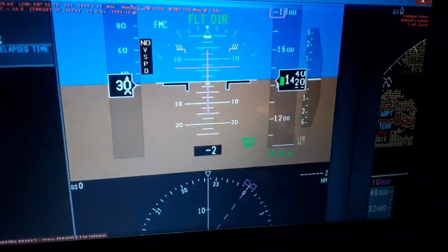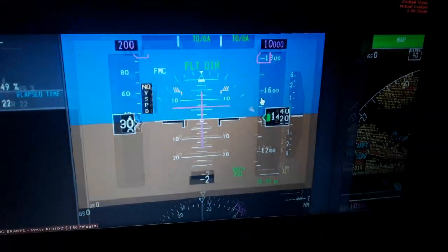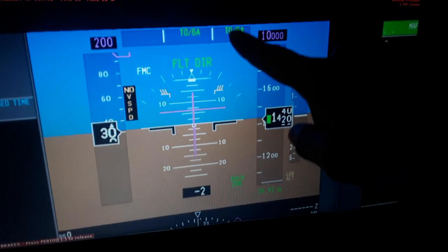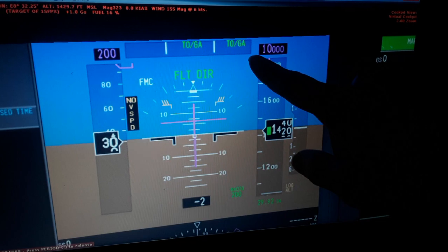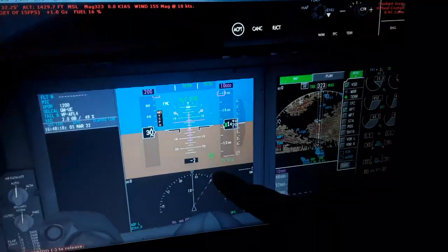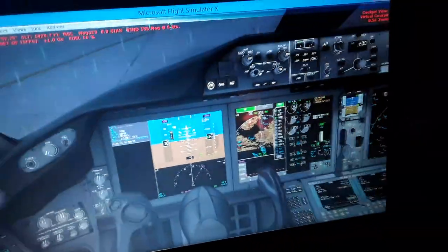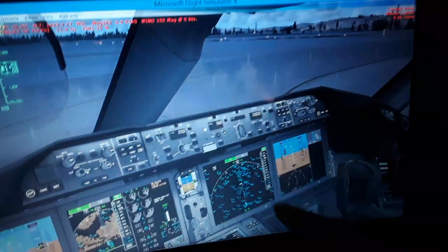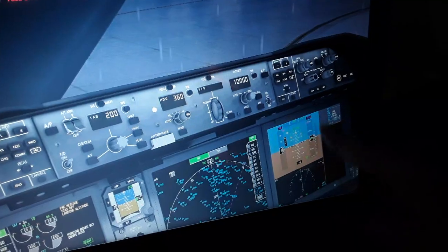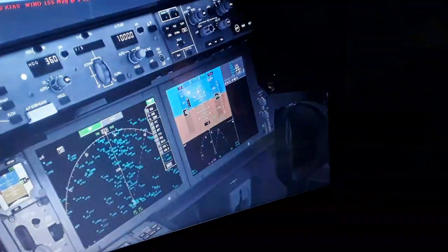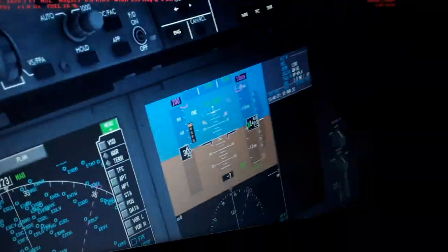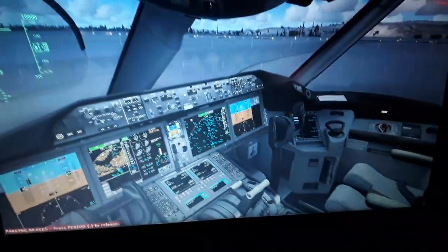Now it's more general. So you can see no V speeds. We have not yet selected the takeoff speeds. Flight mode annunciator with the autopilot, auto throttle, radar and left navigation modes on takeoff ground, and the airspeed 200 knots, altitude 10,000 feet, and heading 360 degrees are all the same as the one selected here. 200 knots, 360 degrees heading at 10,000 altitude. You can see both primary flight displays over here display the same information for the altitude, airspeed and heading. So we're gonna change this later.